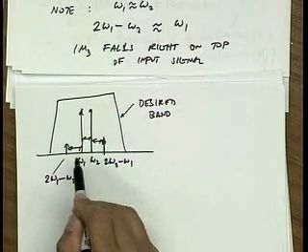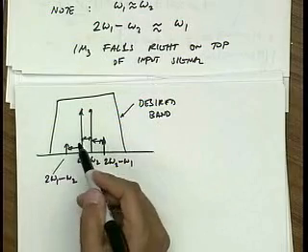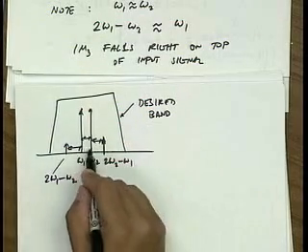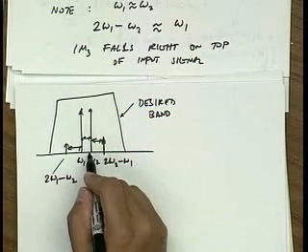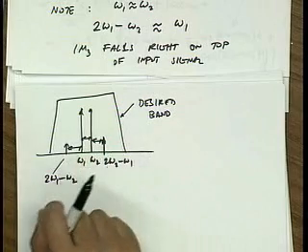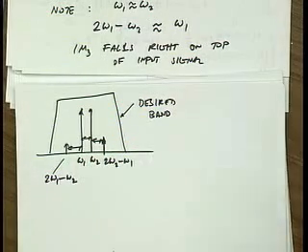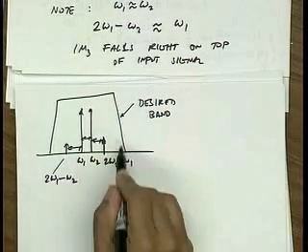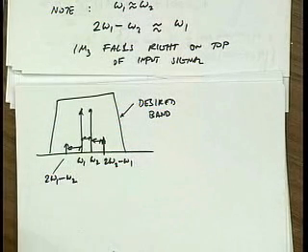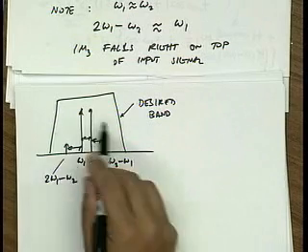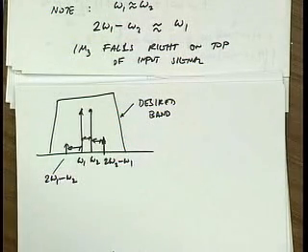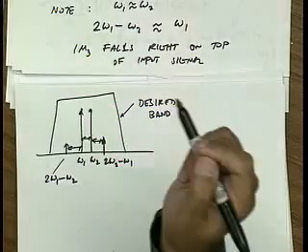And these two tones could represent two modulation components, right? I mean, let's think of a very idealized scenario. Let's say these two tones correspond to two people singing a pure tone, right? Two opera singers producing two tones. The harmonics are out of band, but now this nonlinearity produces two more tones. So we have these two baby opera singers who weren't supposed to be there. And they fall in band. That's the key point. All the other distortion, we could imagine a scenario where we filter them out.